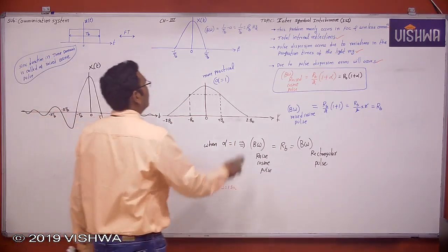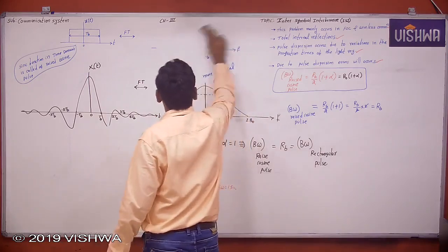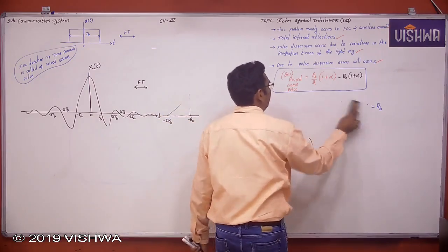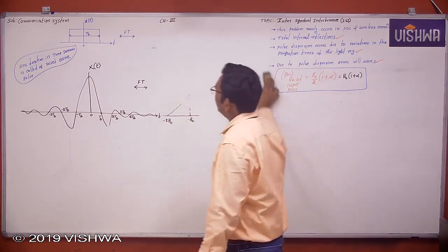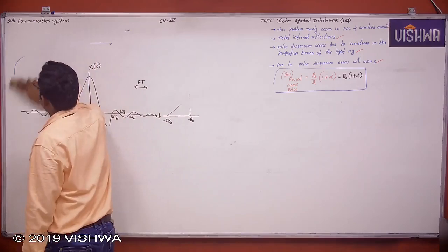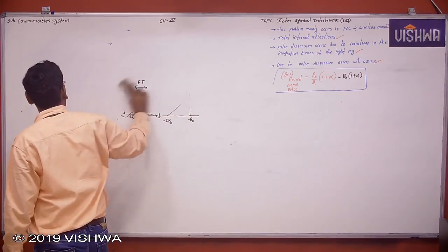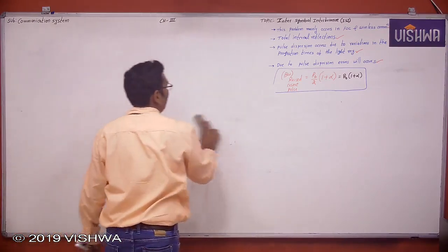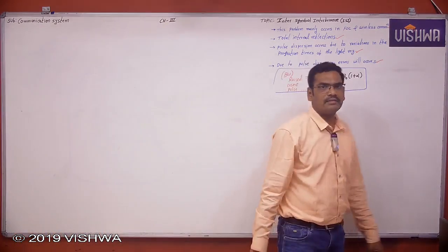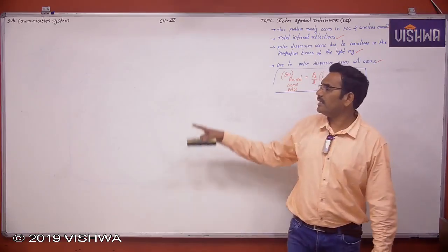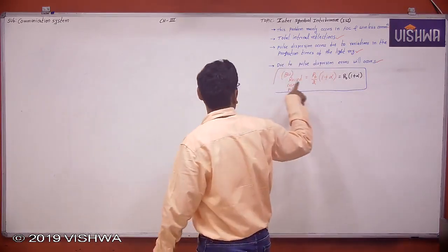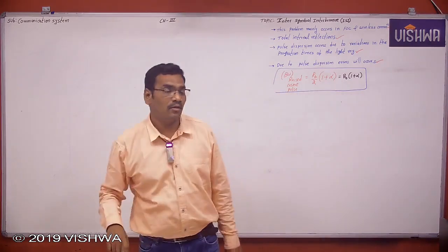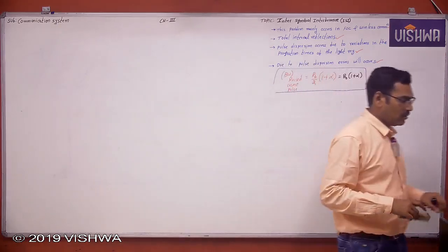This is the intersymbol interference. How to overcome this? Because see, you go back to all our PCM problems. Sometimes in PCM problems, it is said that the binary data is represented in the form of rectangular pulses. If binary data is represented in the form of rectangular pulses, all answers will change. Because if it is raised cosine pulses, now the bandwidth is B naught, which is RB by 2, and the excessive bandwidth is represented by a roll-off factor. Okay. Now one problem is solved here.